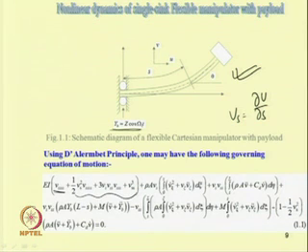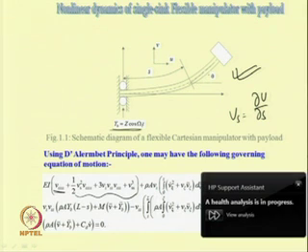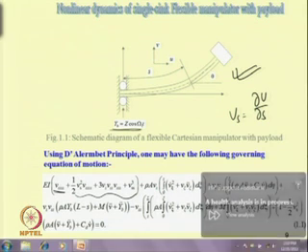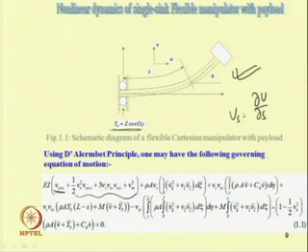displacement, one can write the equation by adding these terms. These equations can be easily derived by using the D'Alembert principle, by considering different forces acting on the system and taking the moderately large deformation of the system. So, this term will come from the stiffness of the system.